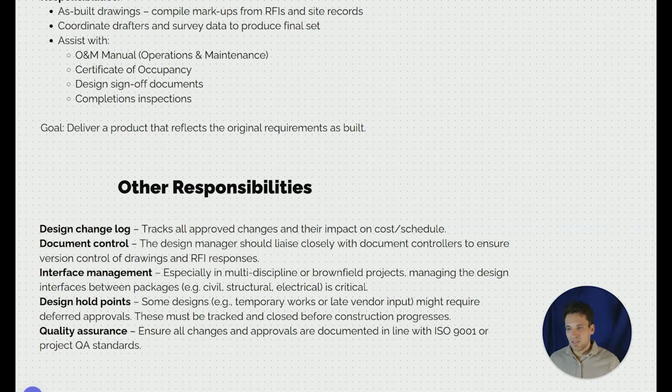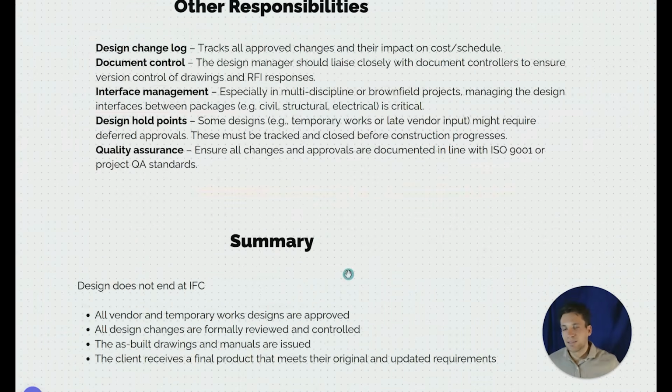Some designs might have specific design hold points that require approvals from the original engineering consultants. You see that a lot in pre-pour inspections and structural work, where the actual structural engineer needs to sign off the drawings or sign off the concrete before we pour concrete. The design manager will typically be involved in that approval, and that ties into the quality assurance process. So ensuring all the changes are made, documents are controlled in accordance with ISO 9001 or specific project quality assurance standards.